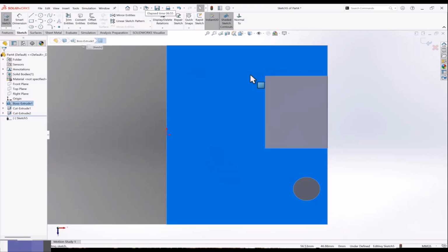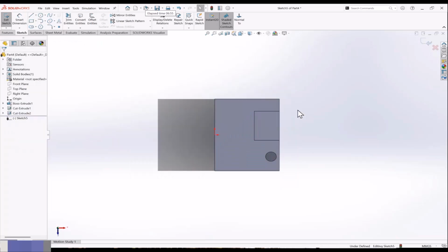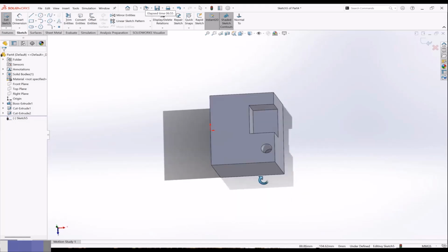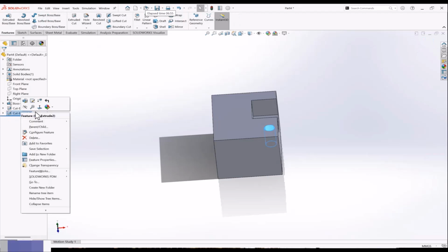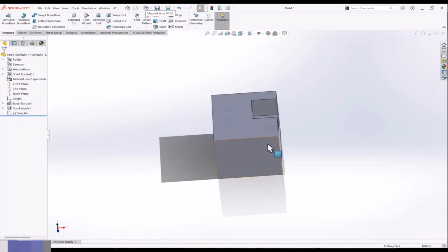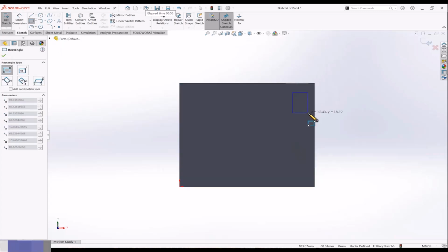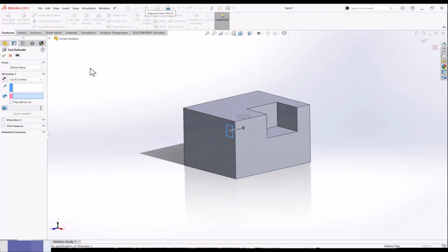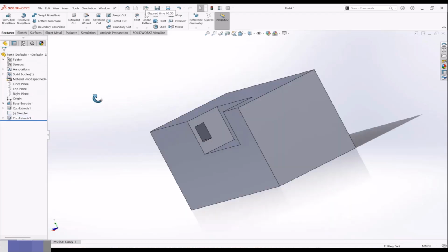Next, you want to cut something till the next feature. If you have anything there on the next side of the body, like I'll go here. Let's delete this extrude cut and then we'll understand it. So I'm going to cut this portion and I'm going to draw something over this face. Okay, let's make something here. I want to cut it. So there is already a cut now. So I'll go to extrude cut and we'll say up to next. You see, it will stop at that face only. Like that, you can use the up to next option also.